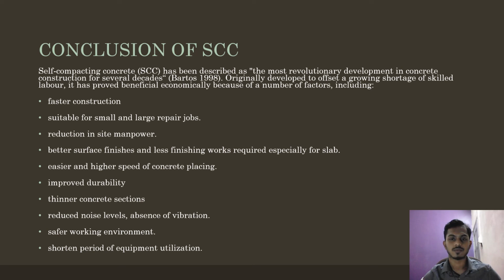Originally developed to offset a growing shortage of skilled labor, it has proved beneficial economically because of a number of factors including: first one is fast construction, second is suitable for small and large repair jobs, third, reduction in site manpower, fourth, better surface finishes and less finishing works required especially for slab, fifth, easier and higher speed of concrete placing, sixth, improved durability, seventh, thinner concrete section,